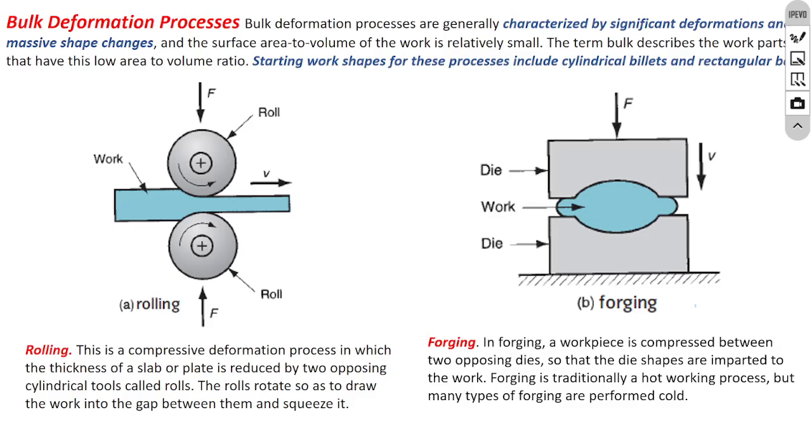Hot working, to decrease the size of the force and the press machine. The solution is to increase the ductility of the material by heating the material before the deformation stage within a furnace.